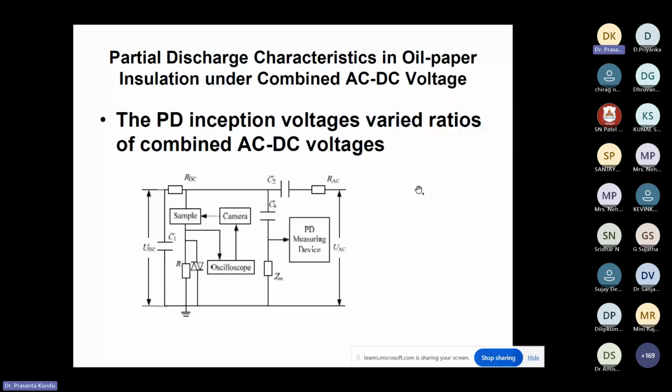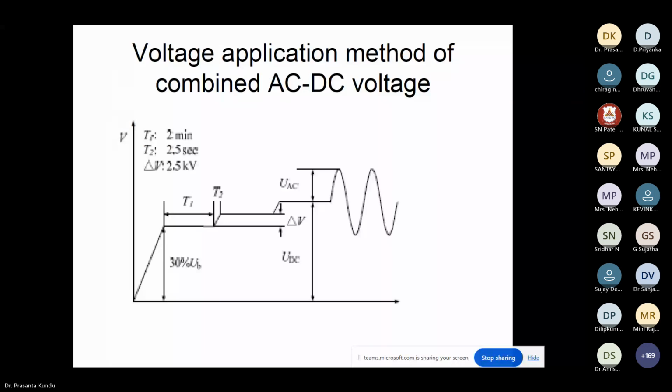Now there are typical applications of the AC-DC voltages. There are different ways PD is measured. First we can have the ramp case, then we put constant voltages, and then you can apply the AC cycles. PD is also measured including the impulses. That means you can have AC and impulses, or DC and impulses, depending on the case, because in normal situations, if PD is not occurring in AC, but there is a minor transient, that is a part of impulses.